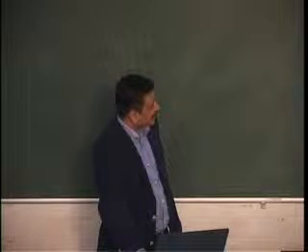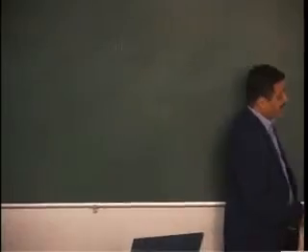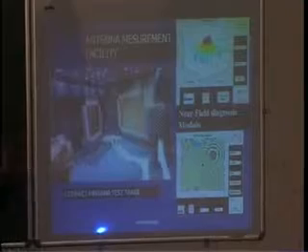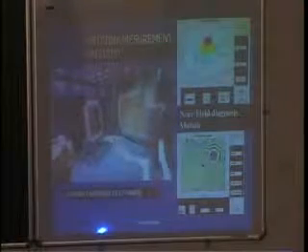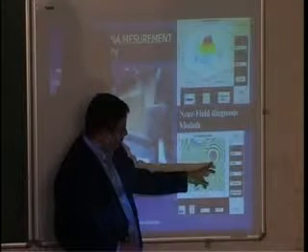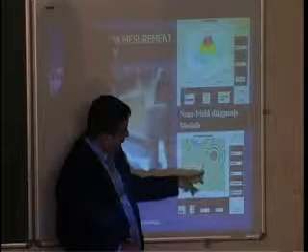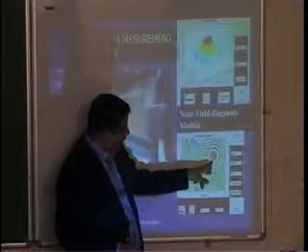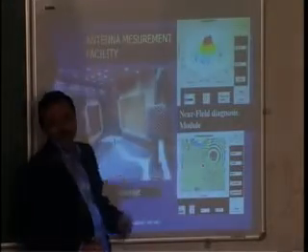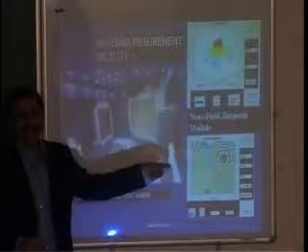So this is how the total setup is. Now this is what I was telling about the far field and near field. In near field, you put a probe near the reflector and start taking the amplitude and phase. Where you have a fault, you see the currents are maximum, with the red maximum in the center, and you see something getting formed here, so you can easily locate that your algorithm is not working properly in the amplitude and phase on the antenna. You can go there, pinpoint that area and correct it.